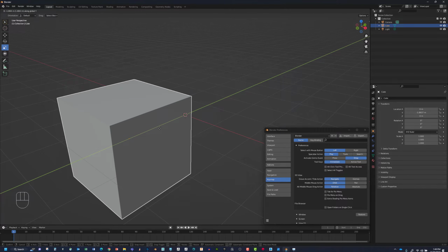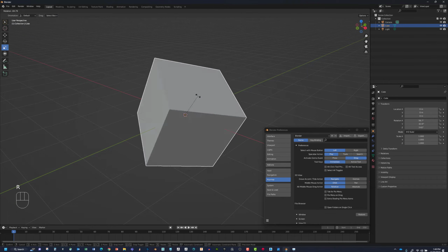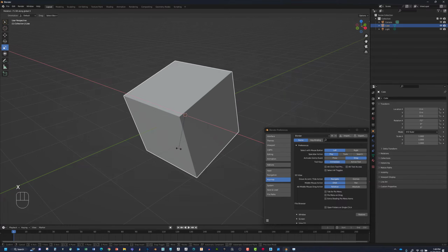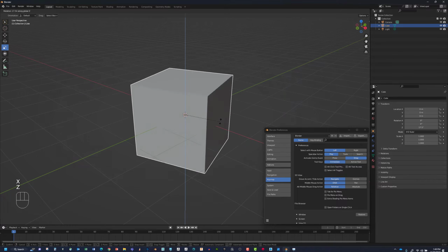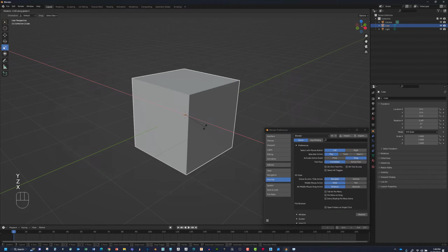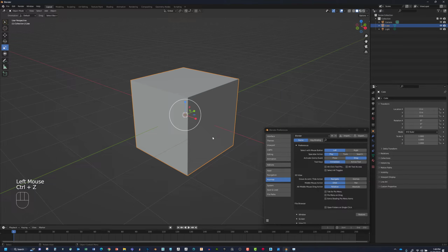And whenever you're done, you can just left click and it's put into this new position. So go ahead and hit undo for that. And if we want to do rotate, we can tap the R key, and this is going to be this free rotate. But again, if we tap X, we can rotate in X, Z, or Y. So depending on how you want to move this object, you just rotate it and then left click to accept it. I'm going to undo for that.